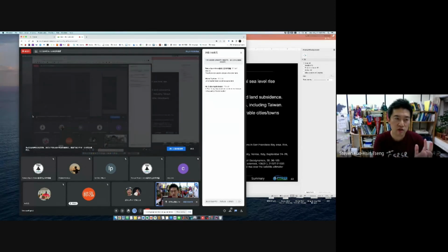The coherence is very important because if the phase is similar in a certain area, it tells you that the solution is meaningful. Only when you have very high coherence are you measuring the same object. If the coherence is low and you still want to solve that, it will give you a very bad, very wrong answer. And it will even pollute everything near this area because there is one step called unwrapping in the InSAR measurement.